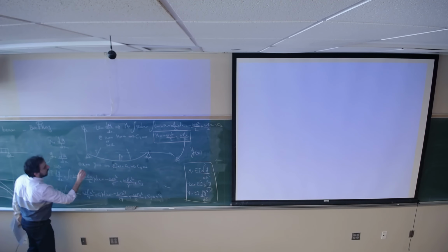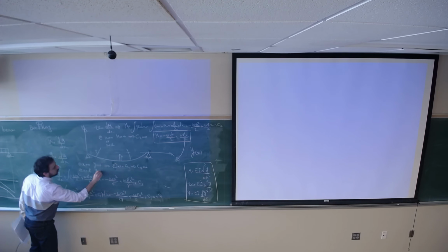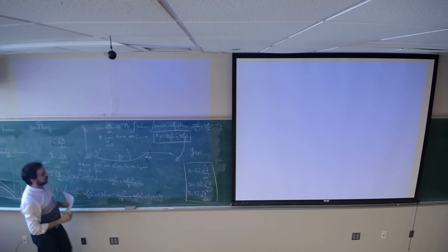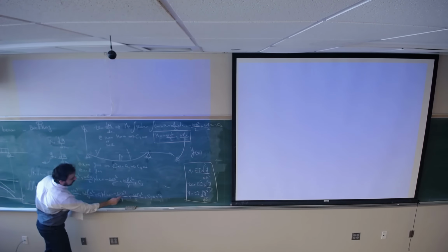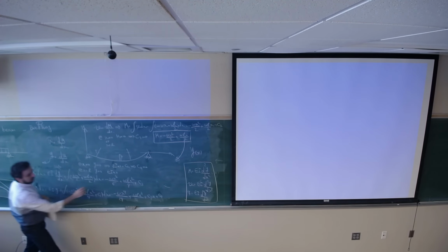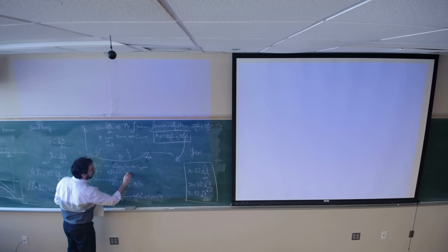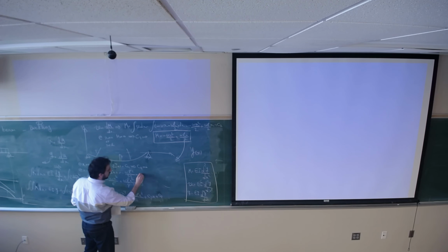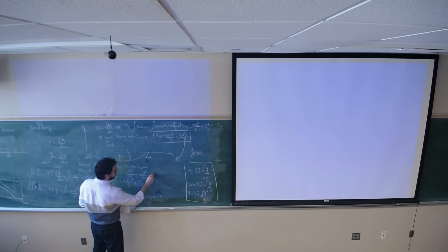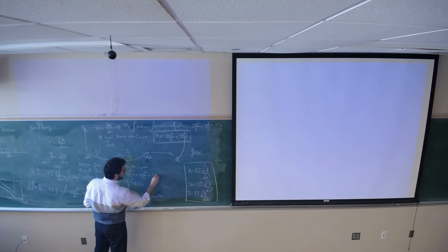Also at the ending point, y is equal to 0. At the end of the beam, we don't have any deflection. So just plug in x equals L. I will get EI times 0 equals negative wL^4 divided by 24 plus wL^4 divided by 12 plus C3 times L equals 0.